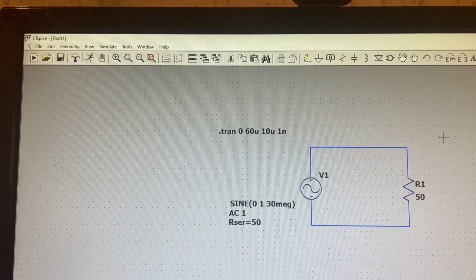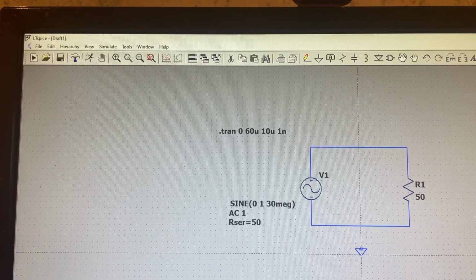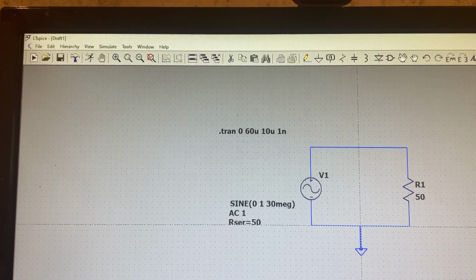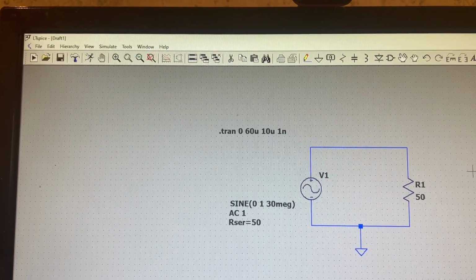And we're all set. One other thing that has to be done is the circuit needs to be grounded. This is one thing that LTSpice requires because all measurements are made with a ground reference. So you see the symbol, I click, drag, and drop, and then I wire it, and that's it. Different sections of the circuit will require separate grounds where you have, for example, DC isolation like a transformer. And I'll show you that as we go on here.